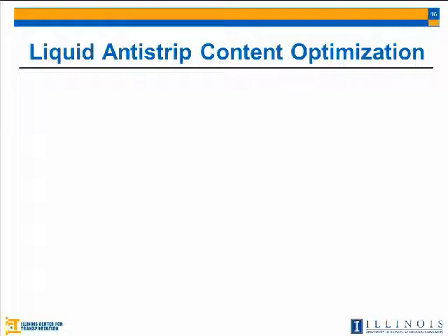Another issue we have to resolve before we continue with the mixture level tests is what liquid anti-strip content we need to use with N70 and N90. To answer this question, we adopted 4 liquid anti-stripping contents: 0.25, 0.5, 0.75, and 1%. We mixed those 4 contents with N70 and N90, and then ran the modified H2 test, meaning conditioning with 5 freezing and thawing cycles.